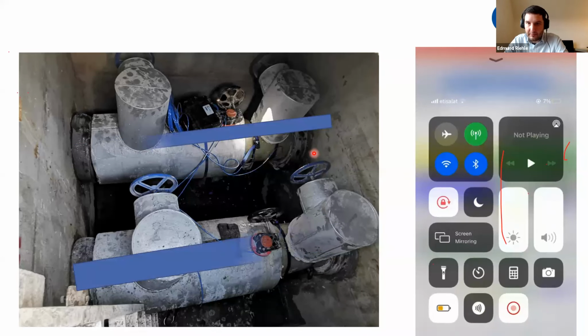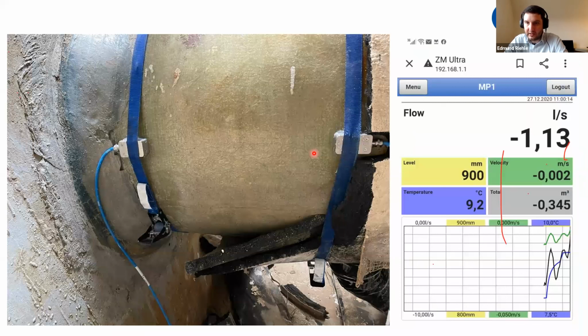Okay. This is another pipe, DN900, and this shows nicely that there is no leak in between. There is a very small, let's say, negative flow velocity, or flow of minus 1.1. That means there is no leak in between. We're still evaluating and defining at what differential flow we can say that this is absolutely a leak occurring in these sections.